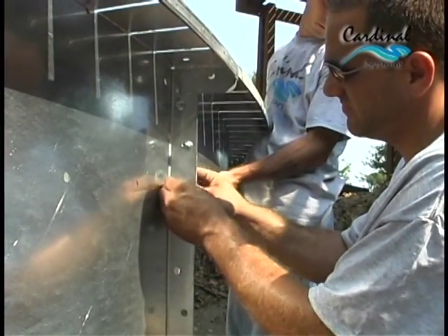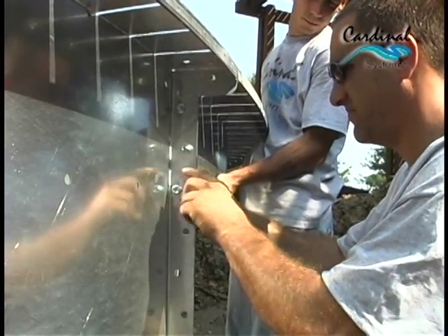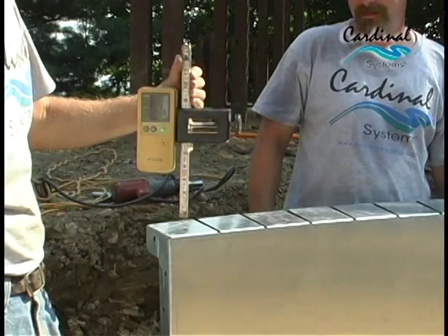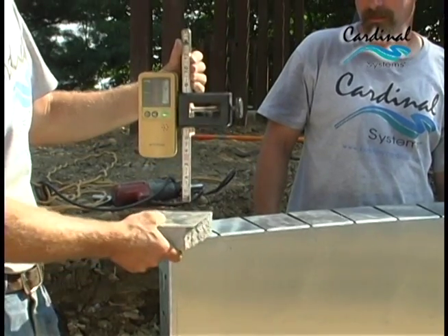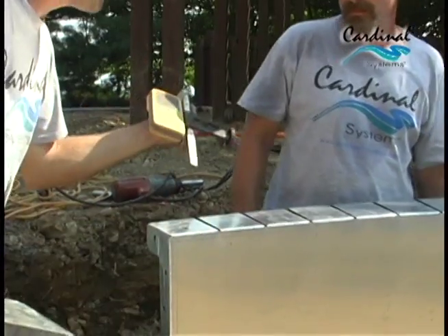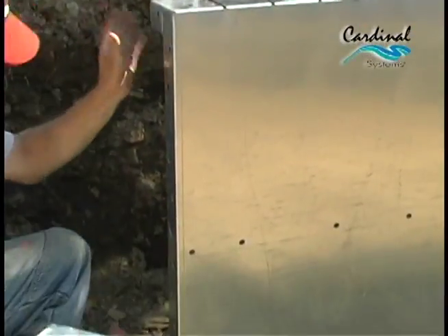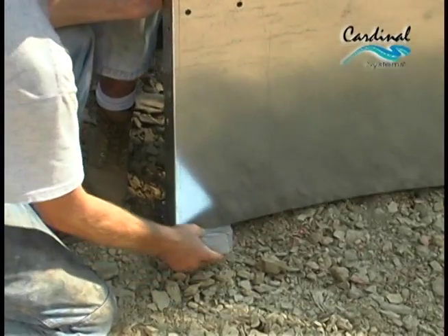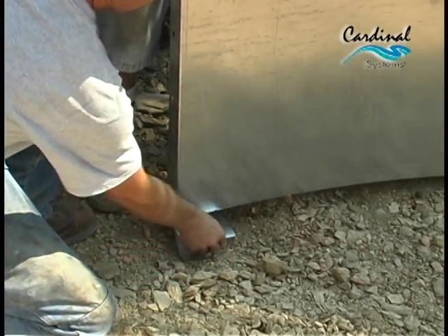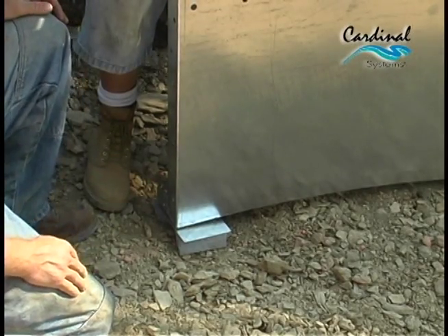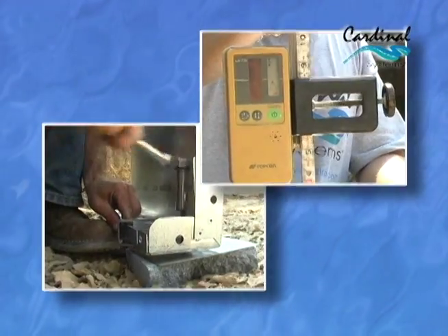All panels are bolted together using the inner holes. The outer holes are provided for plastic step units and other accessories. To level the first panel, take a reading on the end of the first panel. Note that clearly this panel needs to come up approximately 2 inches, or in this case, approximately the thickness of a patio block. Place a stabilizing plate on top of the patio block and insert this under the end of the first panel. This brings the panel up to the approximate height.